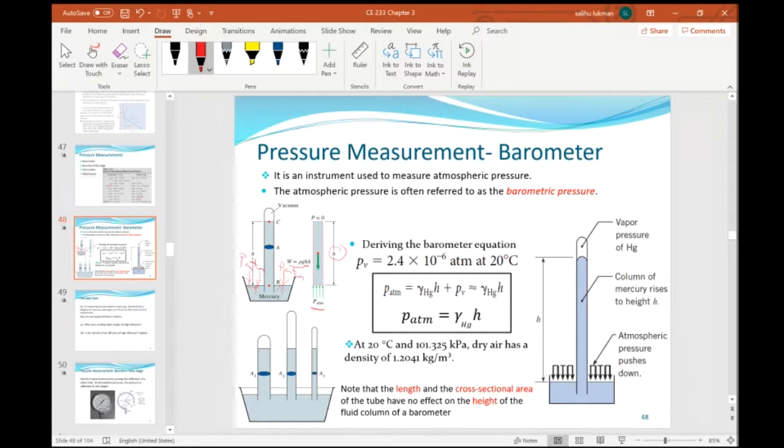This is the weight of the mercury column, rho g h a, okay? That is the pressure times the area, okay? Because this is vacuum, the pressure here is 0. So you have the atmospheric pressure supporting the weight, okay? So it is hydrostatic. The system is hydrostatic.